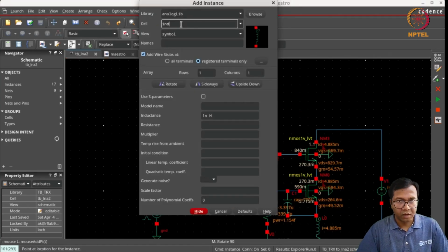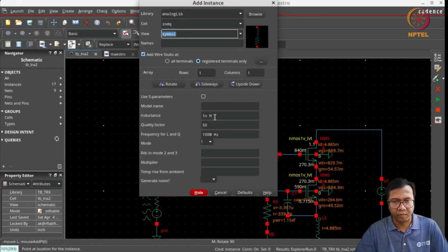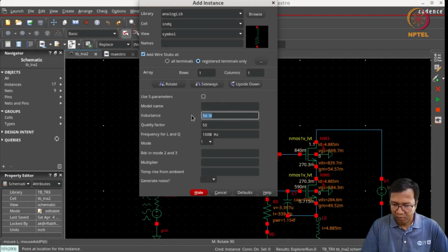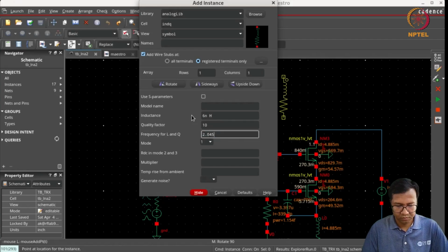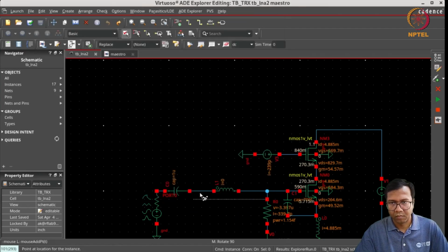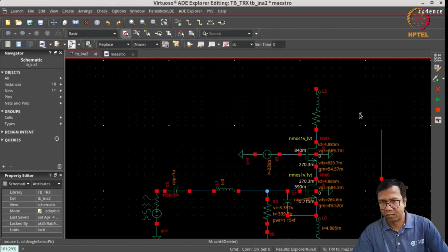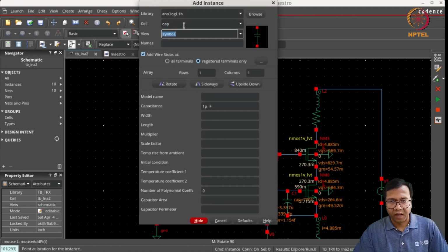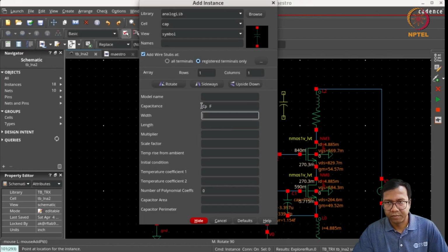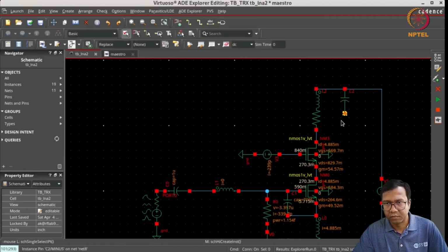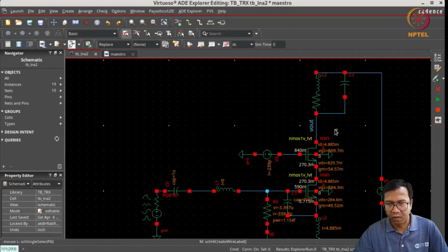We will add an inductor here with a quality factor of 10. And so as to maximize the RP at the output, let's choose the maximum inductance which is possible. And we may need some extra capacitance to tune this inductance. Let's call it CP. What is V out?